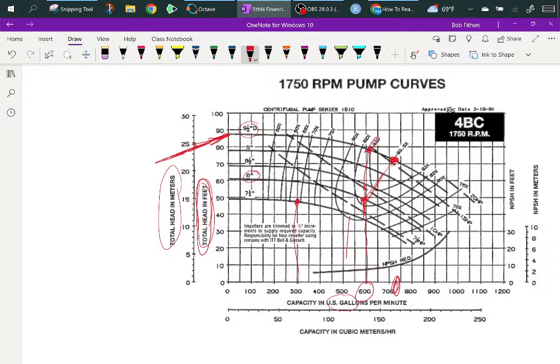Now, if you're pumping it that high, you might not get the flow. I mean, you get down here, you know. So let's say it's 95 feet. Or, I'm sorry, that's 95. So say it was 95 feet. You turn on that pump, it's just not going to make it up there. Yeah. So then let's say you wanted it 80 feet. First of all, this pump's not going to get you anywhere, but this one you might be able to get that many gallons up there, given that the pipes are not going to take away a lot of energy. Pipes will take away some of your energy.